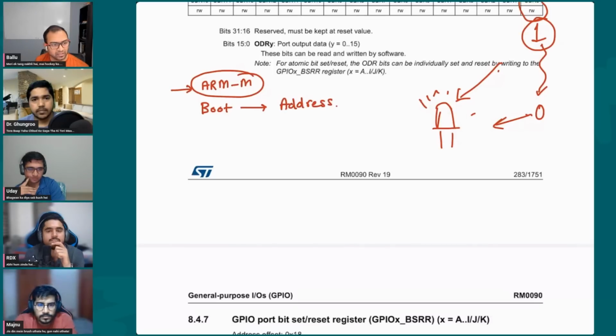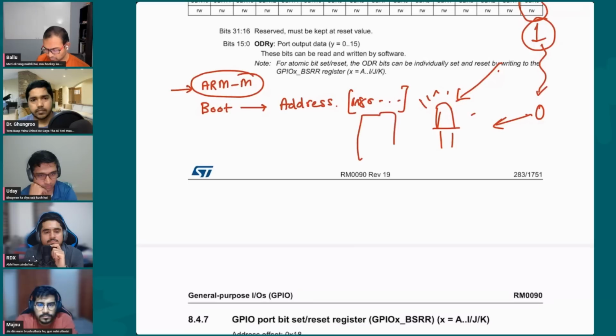In this case, we happen to have some pins that decide which memory region it boots out of. And we just said that it boots out of hex 8 all zeros, that memory region. And then once we knew that, the intention is that we put our stack pointer and reset handler, those addresses starting from this memory region. And we then mentioned that this has to do with the linker script, which is a .ld file.